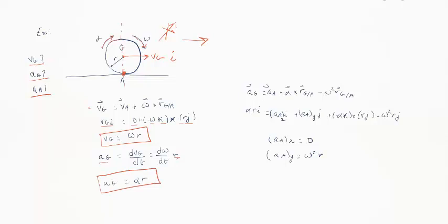Now we want to know the acceleration at A. We set the previous equation that we saw, and then we get AG is basically from what we found over here. We plug it in here, we get alpha r i, and then equals AAX. We separated AA into X and Y component. That's AAY minus alpha k cross RG minus omega squared RG.